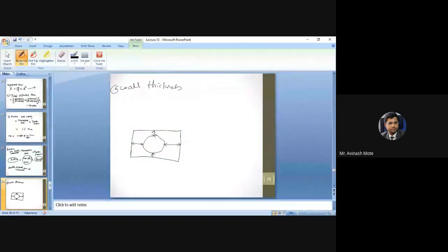Now just understand how you will get this wall thickness. You know the area of the cavity, you know the area of this large mold, subtract that and you will get this one. Are you getting, area or the dimensions? Area or the dimensions. So now what is happening? You will have the available projected area.